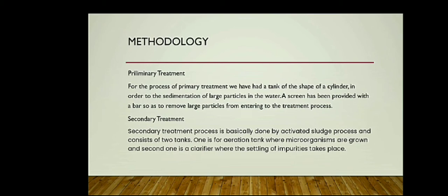Then what is the methodology? First we follow the preliminary treatment. For the process of primary treatment, we had a cylindrical tank for sedimentation of large particles in the water. A screen with bars has been provided so as to prevent large particles from entering the treatment process.